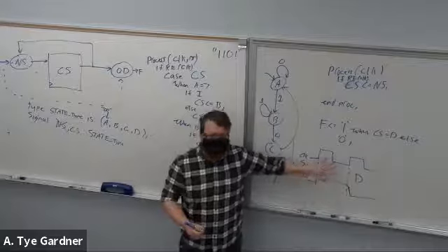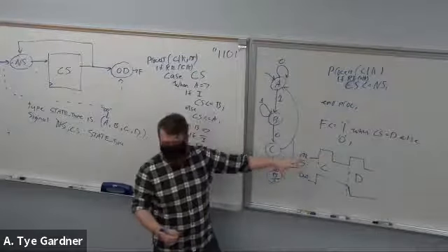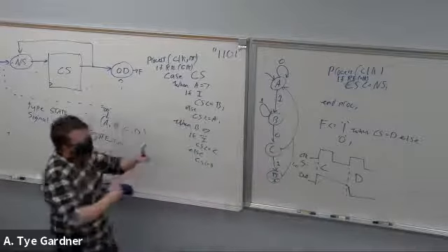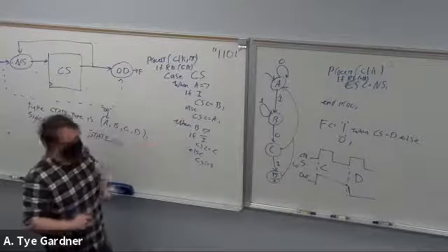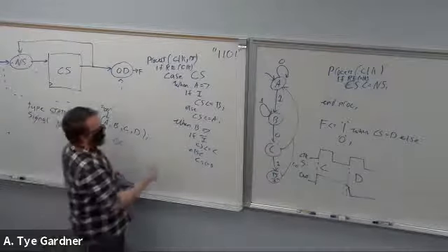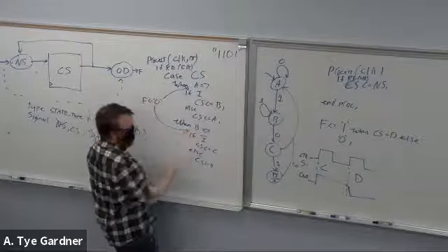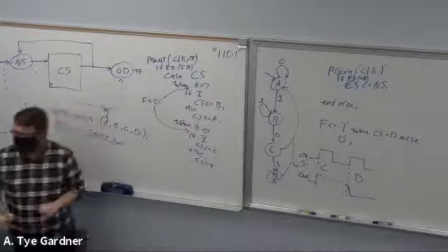It is possible. It's also possible to avoid this depending how you program it. And an easy way is to combine the output decoder into the process, and you just do that by saying, into here, you just say F is 0. Right? Done. Now it is 0.